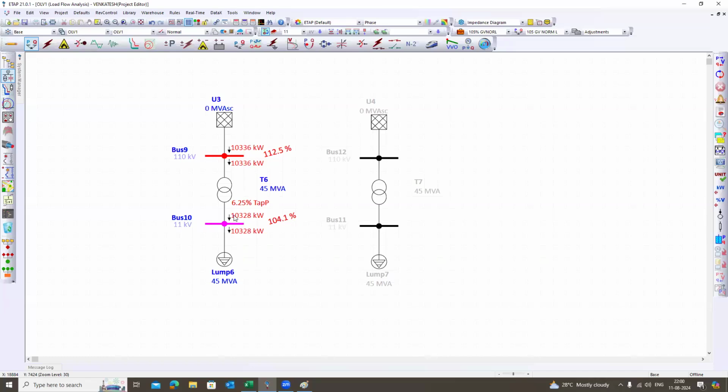Yeah, for intermediate taps, of course, you can do the regulation, right? But our requirement with this tap selection is to maintain the voltage well within plus or minus 5%. That's why you have defined the extreme taps. How do we set the number of taps? No, it's not mandatory. Like in the case of station transformers, there you will have 17 taps also.